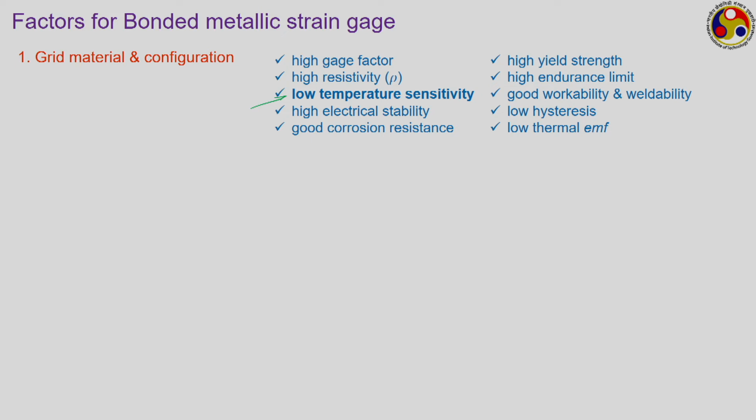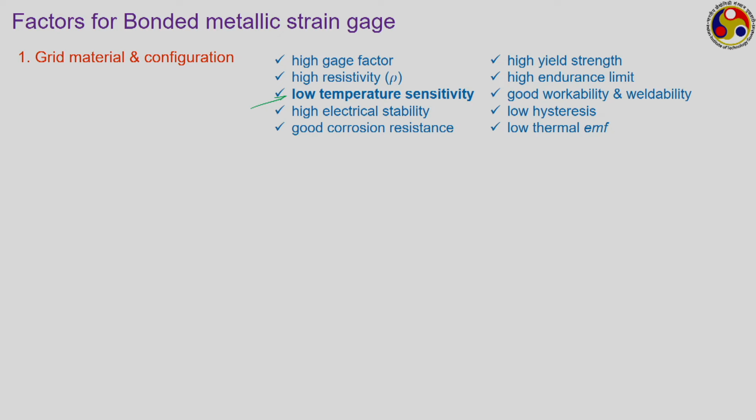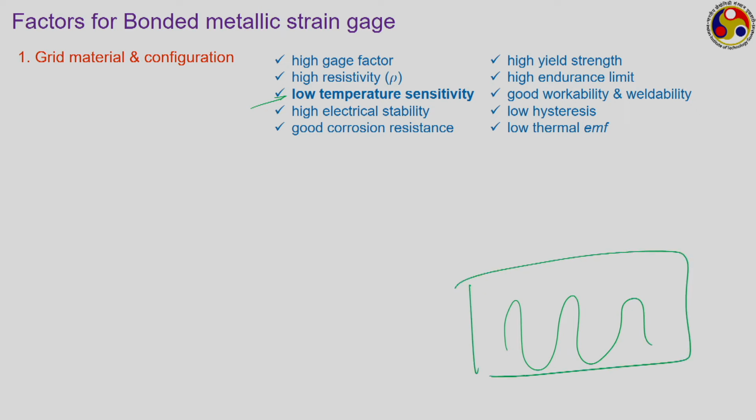We know that the resistance of a resistor changes with temperature, and if the resistance changes, then of course the calibration has to be done freshly, and the output also will be erroneous if we do not do the corresponding correction or compensation. There are two ways the change in temperature can affect the performance. One, you know that the strain gauge materials are connected on some kind of backing. They are generally fixed by adhesive or some other kind of mechanism.